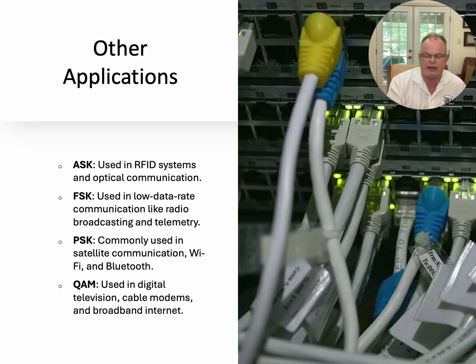Now, other applications: these techniques are used in a variety of fashions. ASK is common in RFID, those little radio frequency tags that you see. FSK is used in broadcasting and telemetry. PSK is used in satellite, Wi-Fi, and Bluetooth. So you're actually using this stuff all the time. You just don't necessarily realize it. Every time you put your earbuds in, you're using PSK. QAM is digital television, broadband internet, all of those things that we depend on every day.